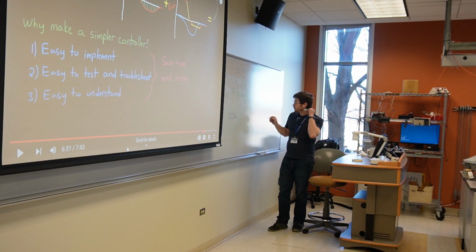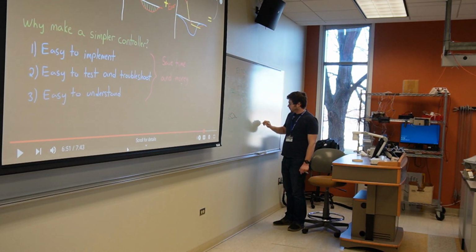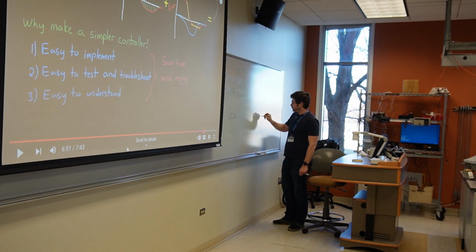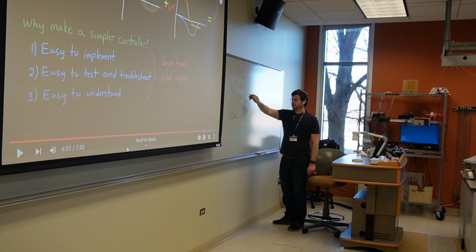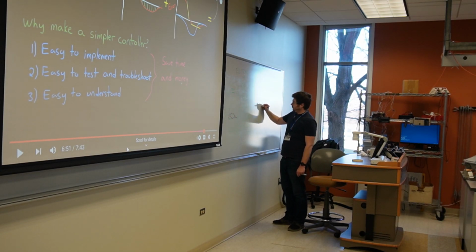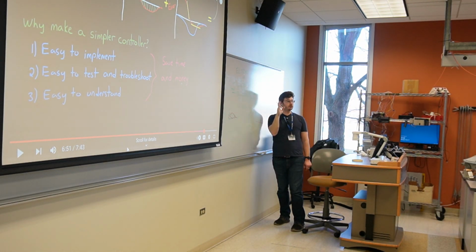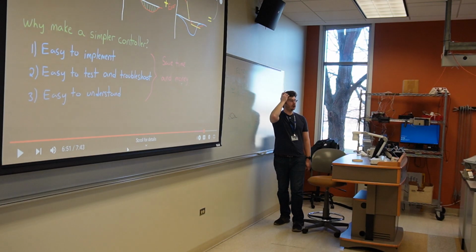So in our tilt example, if we got really close with our P controller, over time, as our integral term adds up, rises and rises and rises, we would see our tilt slowly shift back towards the center. It would slowly error correct. Excellent thing to have in a process control, right? Something that over time will drift towards where you want it to be.